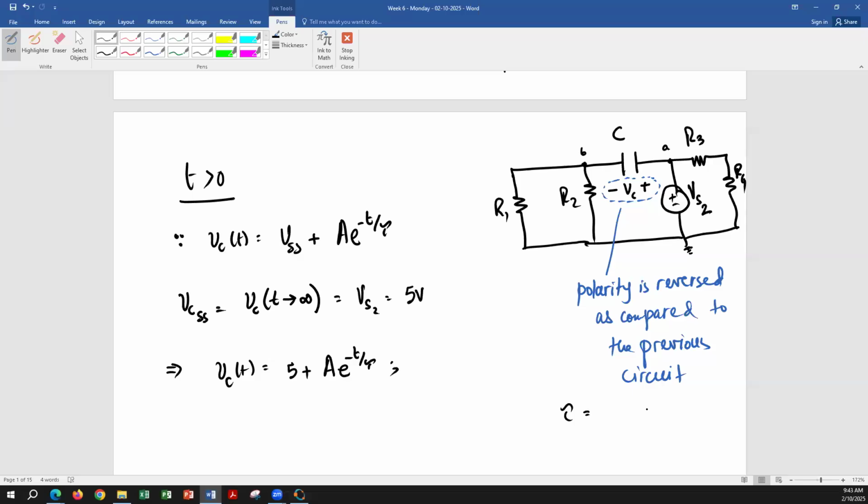Yes, Rodley, you want to take a chance and tell me what will be the equation for tau in that circuit? Time constant. Again, remember, remove the source when you're calculating the equation for tau. Remove the source means if it's a current source, it's going to be open. Voltage source will be short, of course.